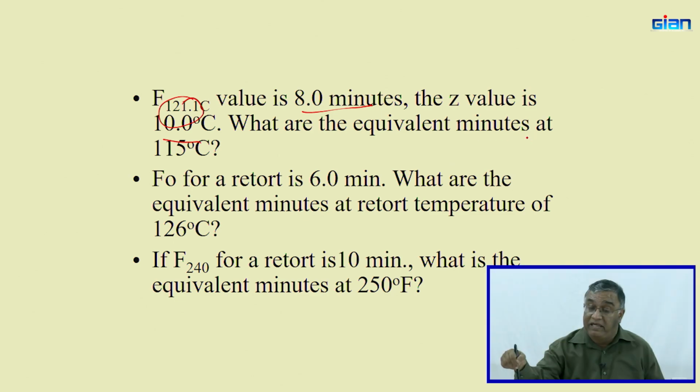What is the equivalent time at 115? Would you expect the processing time to be more or less? It's going to be more, because at 115 your processing temperature is reduced, so it takes longer to kill the microorganisms.